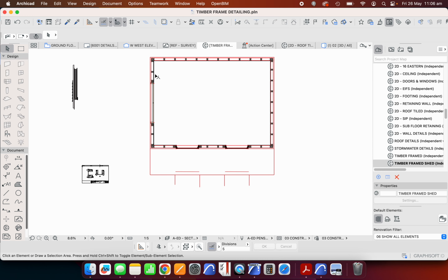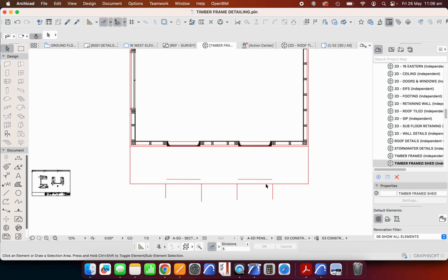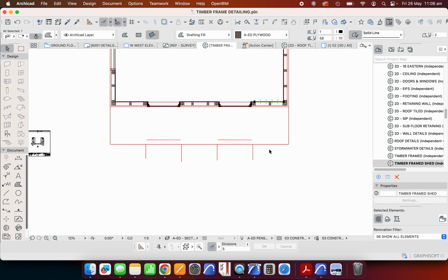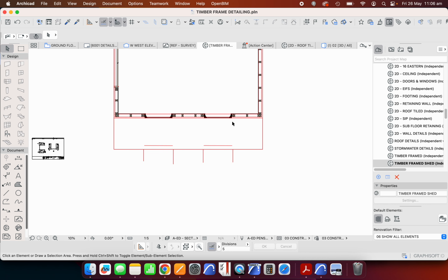And so we've adjusted this left wall based on the double door, and we've adjusted this bottom wall, we call it south, our south wall, based on 2 windows. And we've tried to create those window positions in order to make it centered with the outside of the wall, meaning that it's basically 1, 2, 3, 4, 5 even bays. So it looks symmetrical, it looks consistent. We don't need to worry about the actual length of the weatherboard outside because they're all going to be cut to length. We were trying to be practical with the way that the ply worked, but unfortunately we couldn't do that perfectly because of the size. But we've done a pretty good job of making that work fairly well.